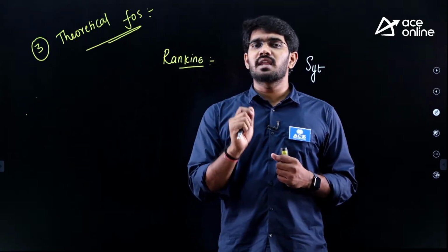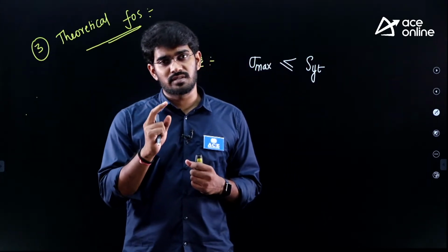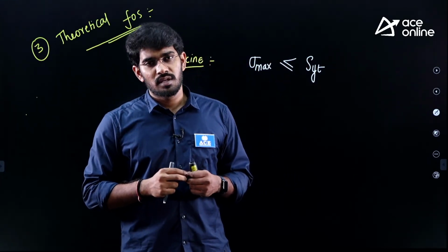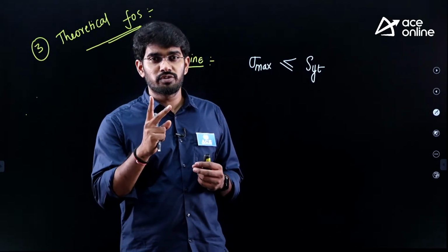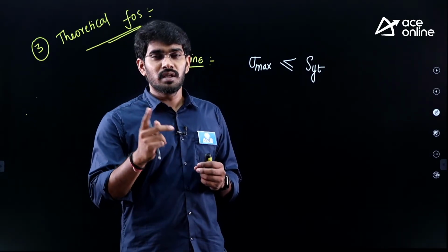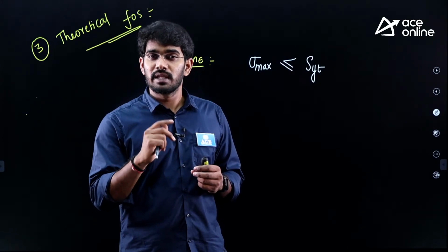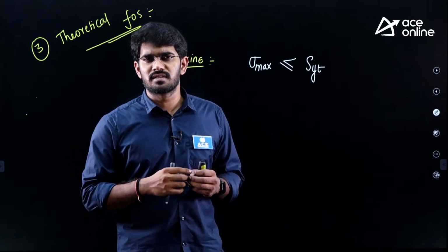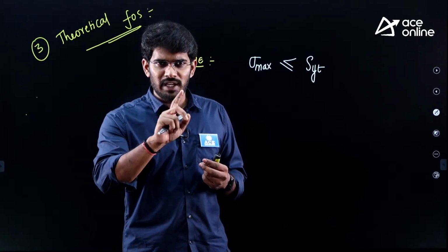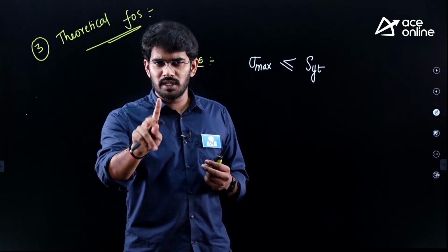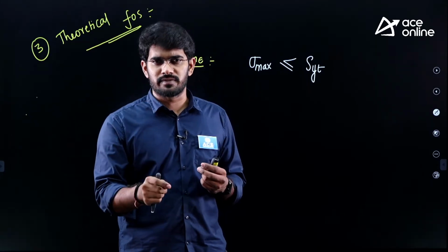The same analysis is even used in the second chapter. If we are considering modified Goodman theory, there are two theories to be used. Remember, that can be either Goodman or yield line theory, which is considered as Langer's theory. Find the factor of safety based on both theories and use the least factor of safety.